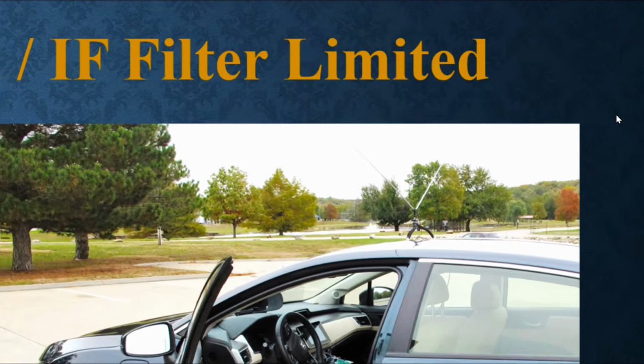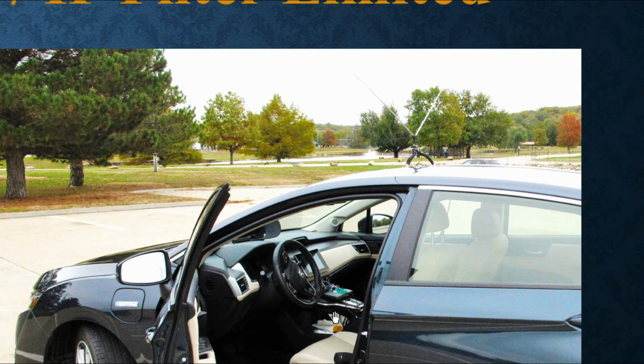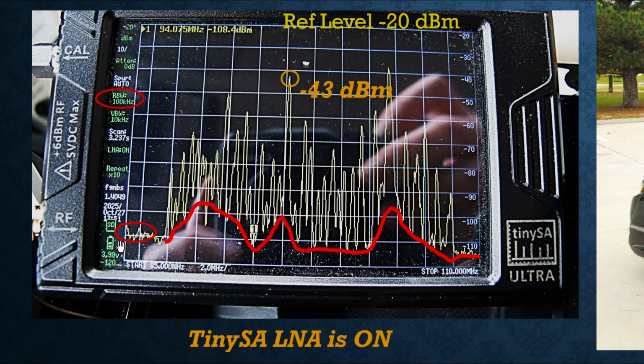And with the antenna on the roof, as you can see here, and routed into the car with the spectrum analyzer, let's see what we get. The noise floor is now minus 110 dBm, which is not perfect, but over here on the right-hand side, it's closer to what we would expect to get, which is minus 120. So where is this noise coming from, and why are these areas so elevated?